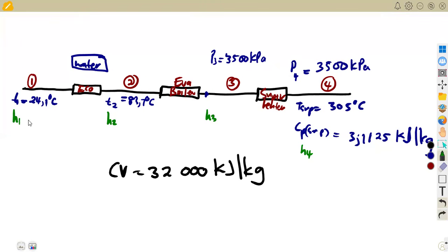So what is going to represent H1? H1 is water that is entering. So the enthalpy for water is our Hf. You know that, guys. That is for water, Hf. When it is dry, H3 is going to be equal to Hg. But this one is not dry, so H3 is equal to what? To H wet. You must know this. I talked about this from our N5. So they are assuming that you know all this part, because that was our N5, if you take note. So where do we find Hf?